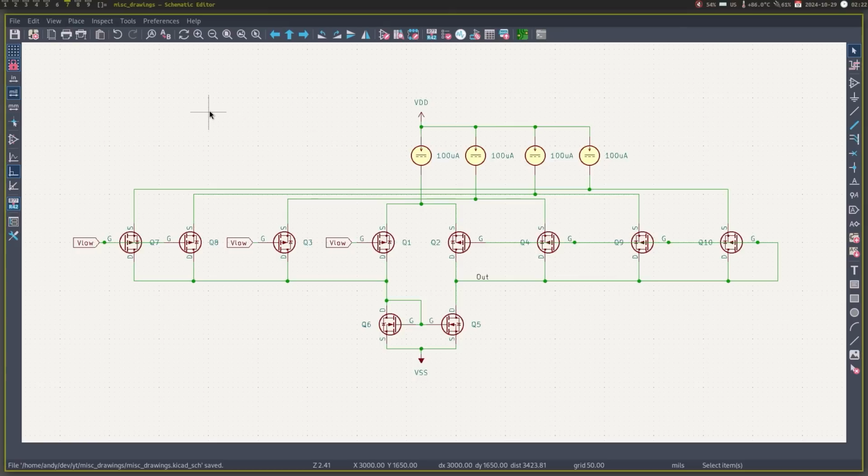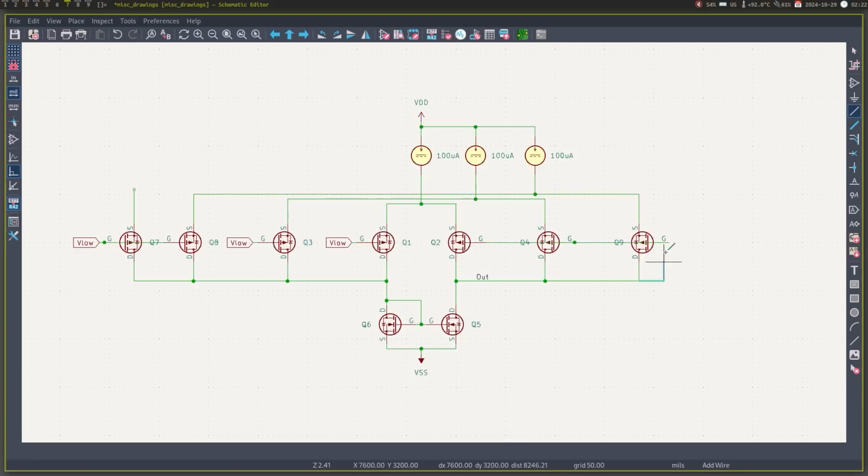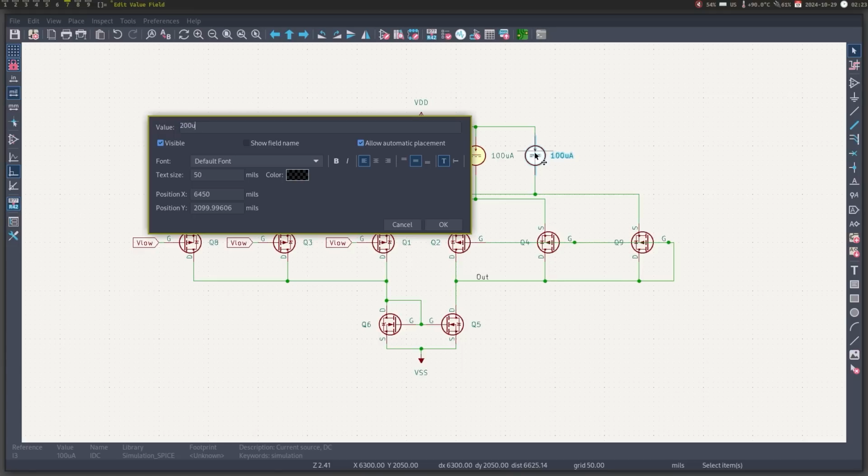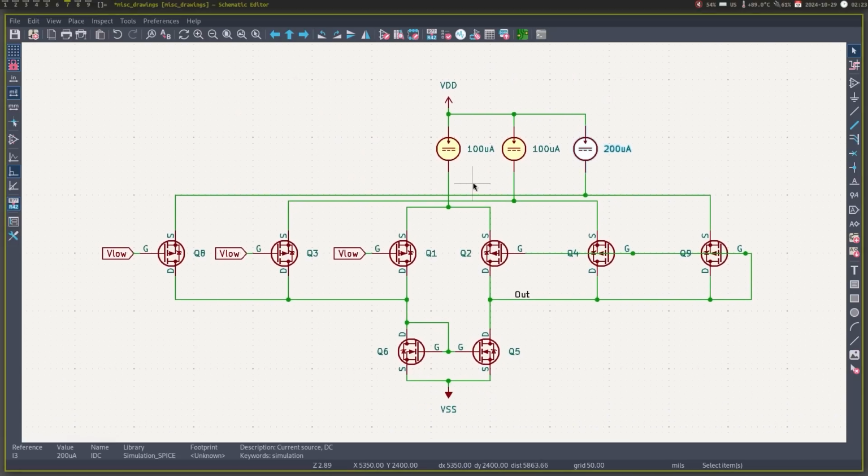You will also notice that we run into the same exponential problem. But this is okay, since we are reducing the number of bits anyway by cascading DACs, but we can still improve on it. Instead of using 2 differential pairs with the same current for the second bit, we can use 1 differential pair with double the current. So, instead of using an exponential number of differential pairs, we are using an increasing current. This is a really nice trick to save space. But it does degrade linearity performance since the pairs are no longer identical.